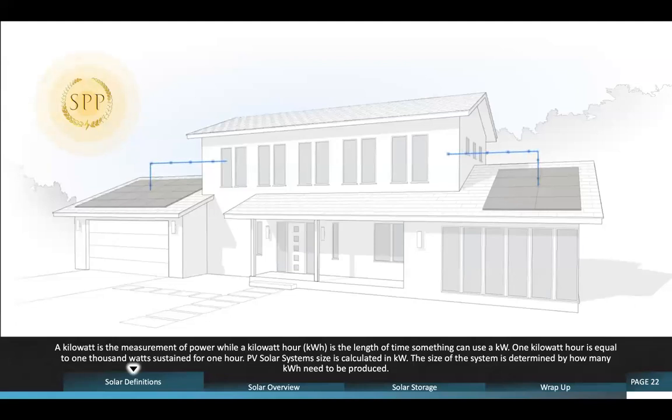So a kilowatt is a measurement of power, while the kilowatt hour is the length of time that something can use a kilowatt. 1 kilowatt hour is equal to 1,000 watts sustained for 1 hour. PV solar system size is calculated in kilowatts. The size of the system is determined by how many kilowatt hours need to be produced. This is what we're trying to accomplish. We need to know how many kilowatt hours a customer has so we can build a system in kilowatts.